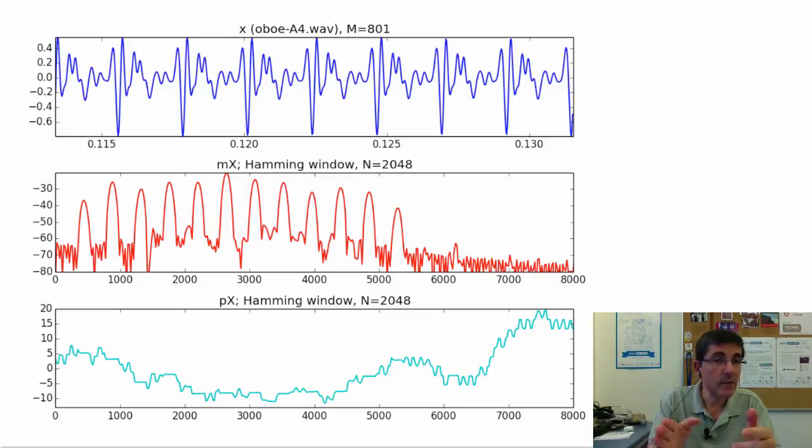And so here, because we took more samples, the distance that now we can discriminate is smaller. In fact, we see that the main lobes are narrower than what we even need. That is, we even see the side lobes in between the two main lobes because we took a bigger window size, and therefore we are able to discriminate even more than the fundamental frequency.